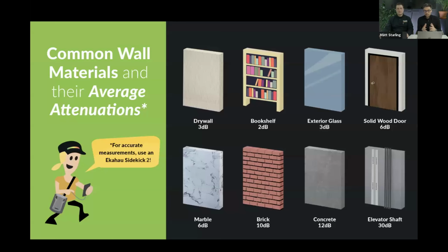That's called reflections. Other pieces of material can actually cause something called diffractions. So as an RF wave hits a piece of material, it can actually bend around it. And the reason why I mention that is because when you visualize heat maps in Ekahau, we automatically calculate for you what happens with that natural degradation of the signal from your radio.